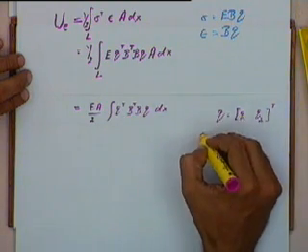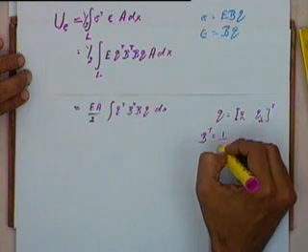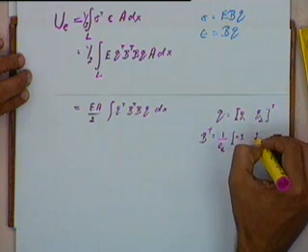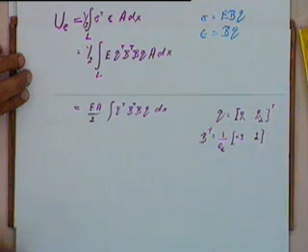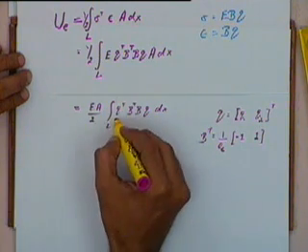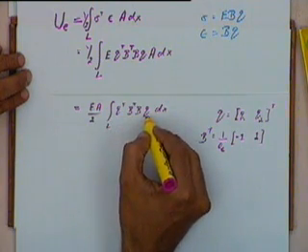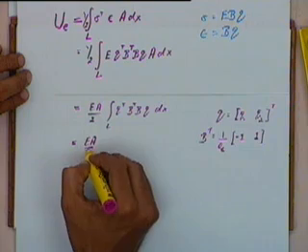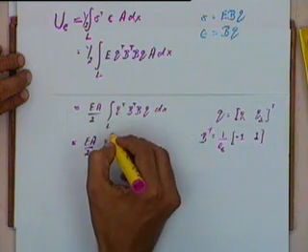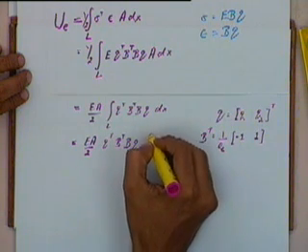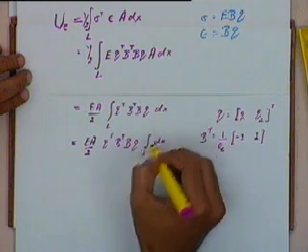Similarly, B we said was equal to 1 over LE, where LE is the length of the element, multiplied by minus 1 1. So B is also a constant, it does not vary with x. So in this integral over the length, all these 4 terms are constant terms. So this will be equal to EA by 2 multiplied by Q transpose B transpose B Q, integral over the length dx.